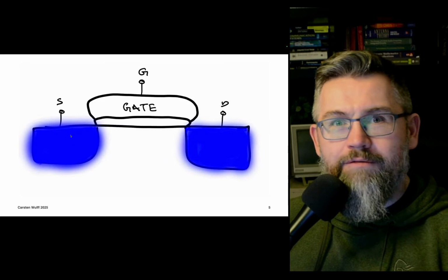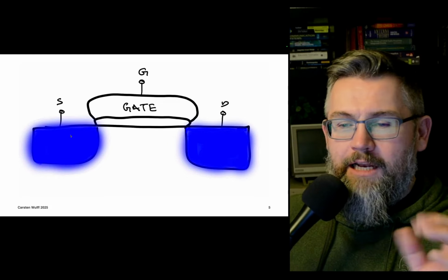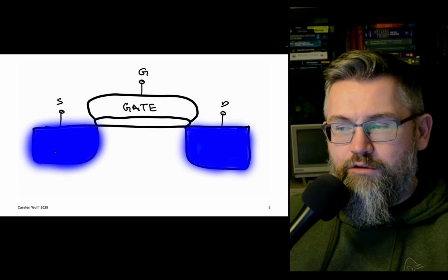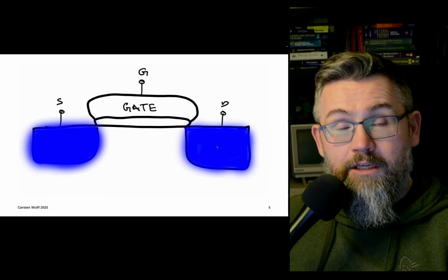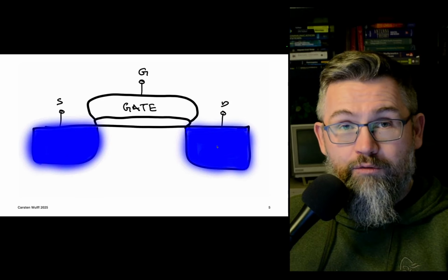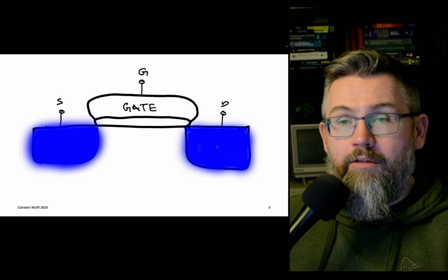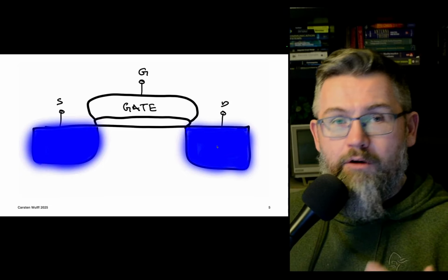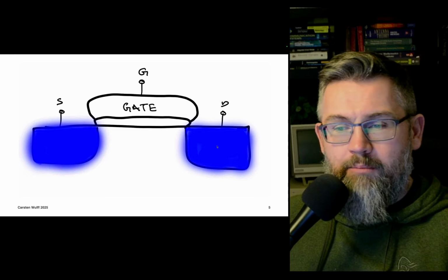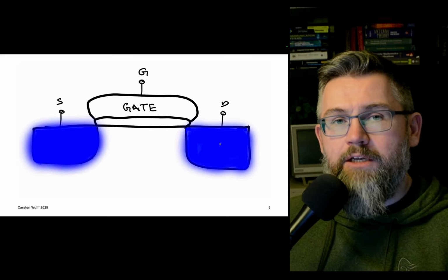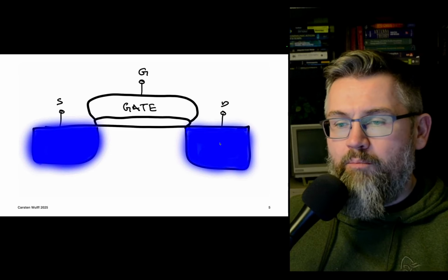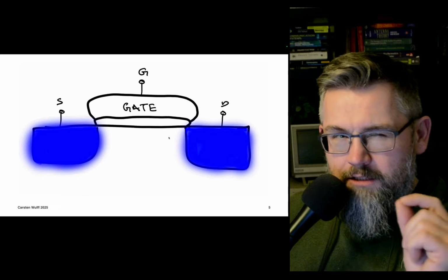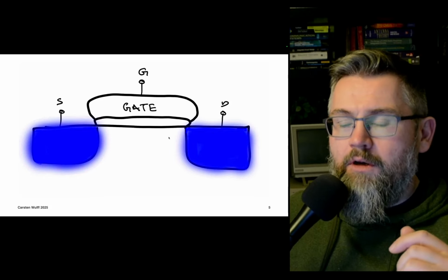The blue stuff, that's the free electrons, the electrons that can contribute to current. In the source and the drain regions, we have added phosphor atoms, which have an extra electron, and those are very easy to release from the bound state. So they're floating around. They're free electrons. And that means that both the source and drain are relatively low ohmic. But they cannot flow from source to drain in this picture. They actually do flow a little bit. We'll talk about that later.